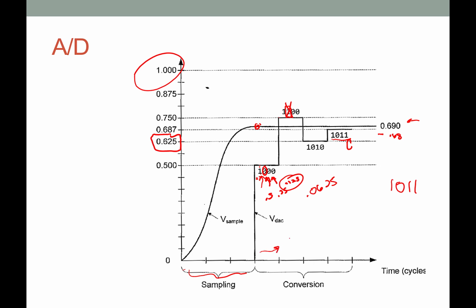The first time gets our first bit, then our second bit, then our third bit, and then our 4th bit, and we're done. So if we have an 8-bit successive approximation converter, how many times does it take to go through it? Well, 8. You have to go through this process for each bit. Now this is for the successive approximation converter.